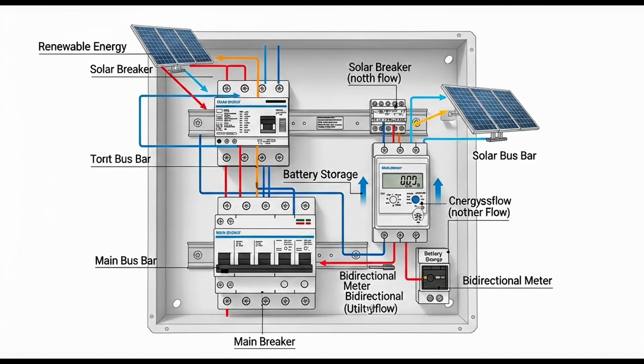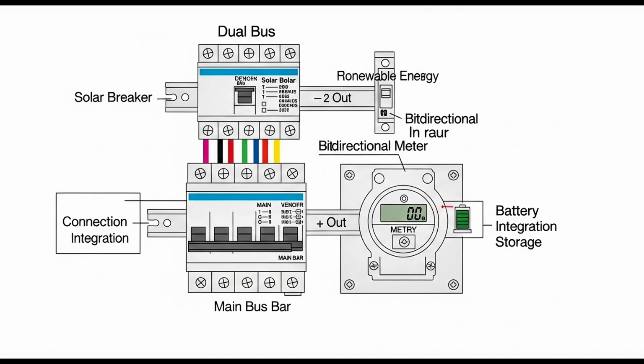Another issue is outdated equipment. Panels installed before the 1990s may lack modern safety features. Some older panels, particularly certain brands from the 1960s through 1980s, have known design flaws that create fire hazards. If you have an older home, having an electrician inspect your panel is a wise investment.